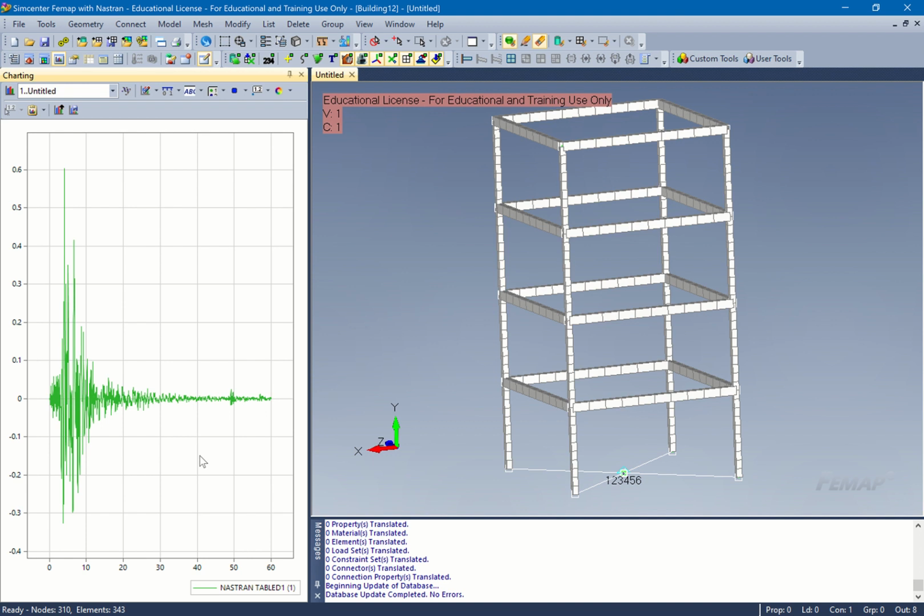You can actually see it's very common for an earthquake to build up the rumbling, the low frequency stuff that comes from the P wave. Then the building large acceleration, and then you have a taper off. So this is time, a 60-second track. But really, we're only going to run it out to 10 seconds, maybe 20 seconds.